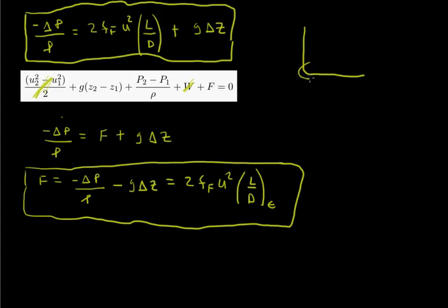We're going to have quite a bit more frictional effects in this region, in this elbow, but we can characterize that by an effective length over diameter. So we can still use this derivation, and we just have to take into account an effective length over diameter. And there are tables in many fluid dynamics books that give you an effective length for a 90-degree bend elbow.